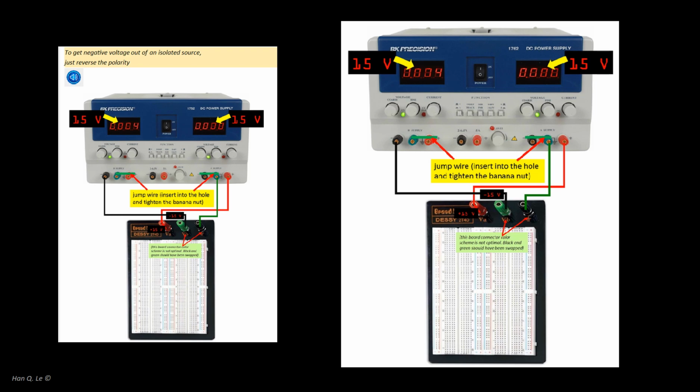The color coding scheme is helpful to reduce risk of errors. The green color binding post on the board matches with the green color banana connector on the BK power supply, which serves as the ground. It is the same ground green color convention in household electrical wiring. The breadboard red and black binding posts respectively match with their counterparts on the BK.